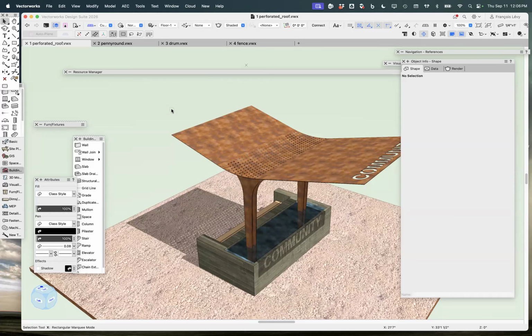And you can see that I've got all these perforations that I have selectively placed in the panel. So this is a really great application of a perforated panel for a surface array. Now, most of the time when I'm doing a perforated panel, I might just resort to using a RenderWorks texture onto a solid surface.